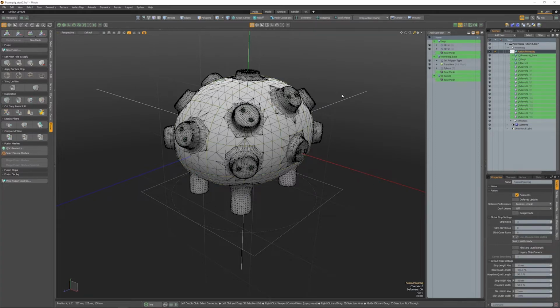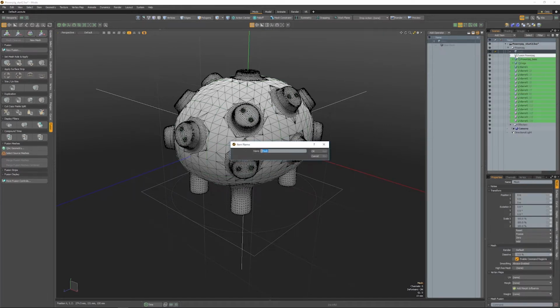One extra step that I will teach you, it's not mandatory, just I like to do it. You see these triangles? I don't like it. It's just a representation of Meshfusion. They will not be visible in the final mesh, but it's just visually I don't like it. So workaround for this is N for new mesh. You just click N. With a new mesh, you just rename it.